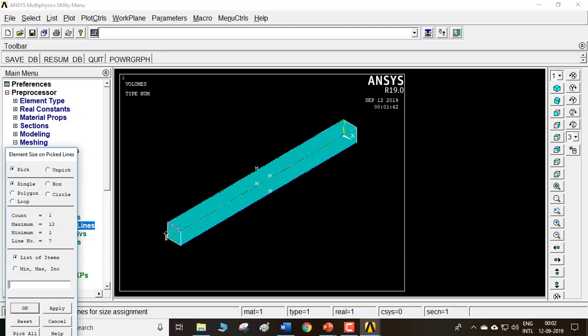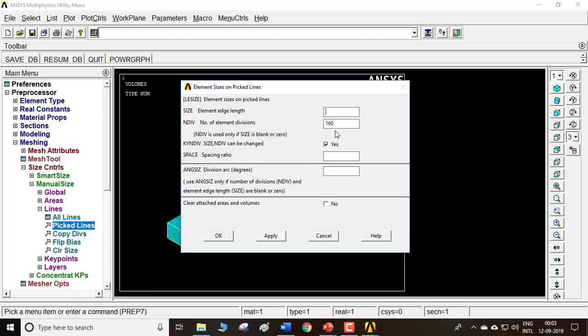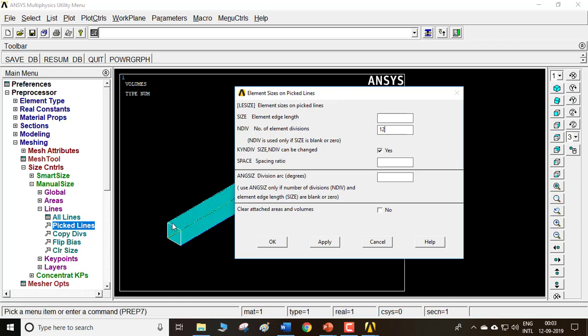I'm going to select the shorter lines here, 1, 2, 3, 4, and these shorter lines along this square here, right? So in total I have selected 8 shorter lines. I'll click on OK. Now I'm going to divide all of this into 12. And again, as I told you, it's not necessary that you select the number of divisions the same as the length of this line.